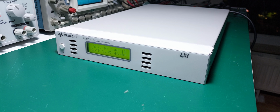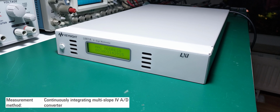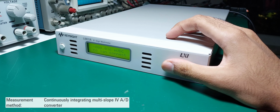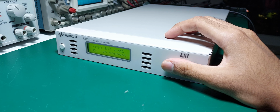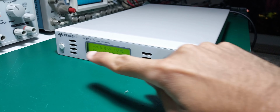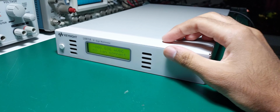What might have turned into a long, boring video filled purely with theory and speculation was saved by Max from the Reps Discord, who loaned me his L4411A. The L4411A, along with the 34410A, uses a Multislope 4 ADC. The L4411A is a stripped-down rack-mounted version of the 34410A, and therefore lacks any trace of a user interface.